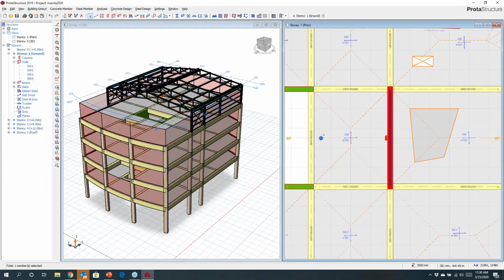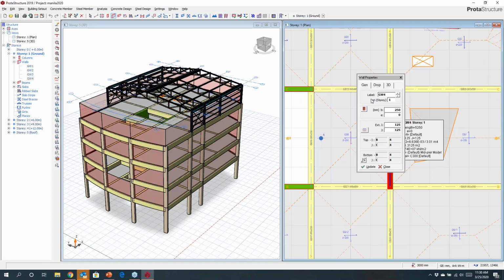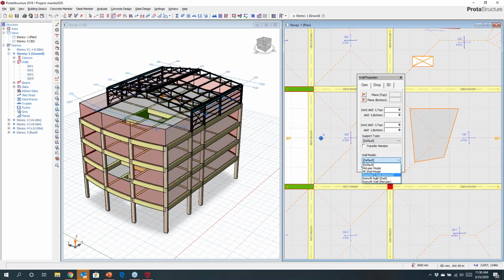If you are selecting, say, a wall, now we have different types of walls within the program. So it's just not general shear walls. We also have what we call basement walls. If you were defining a basement wall, it will be automatically meshed. And once we create a basement wall, we then know that we would proceed to look at doing a two-stage analysis for seismic.